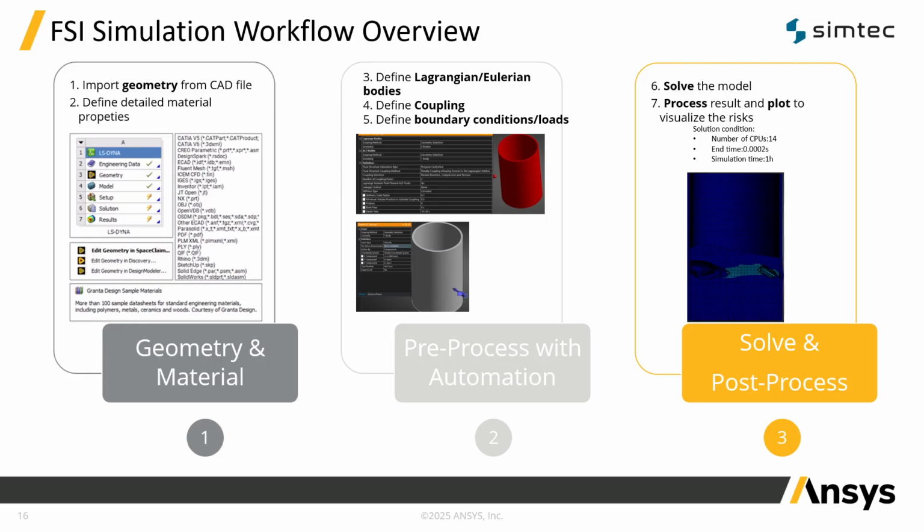Here we must define the Lagrangian and Eulerian bodies. Solids usually are Lagrangian, mesh moves with the material. Fluids use Eulerian or ALE, arbitrary Lagrangian Eulerian, fixed or deformable mesh, or SPH, that means we'll define it as particles.